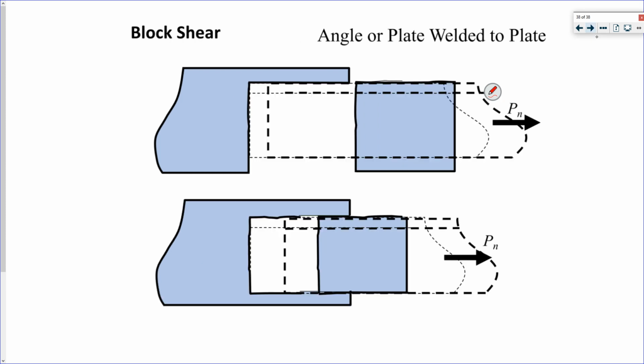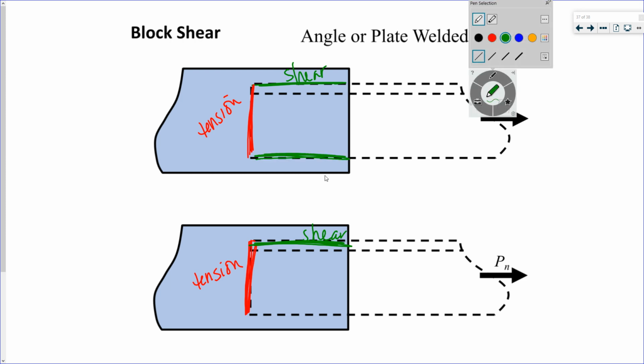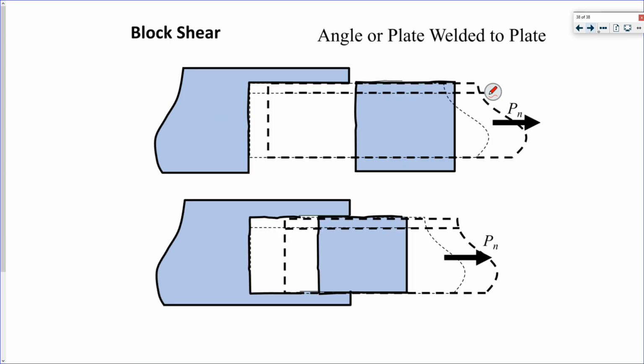Oh, I chose poorly. I was backwards. I should actually look at my notes what I'm doing. Right. So you could have the rectangle, this whole section, or the corner, block shear off, like that. Right, so again, this is my tension plane.